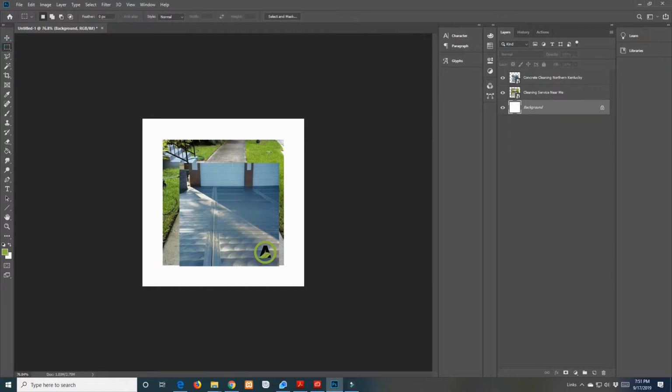Your shape tool. So I'm not going to really go into the shape tool right now. You can just draw shapes. So we're on square, so it's drawing a square. If I do, you can do a circle. If you just left click and drag out, it's going to get all distorted. Control Z it. If I hold Shift, we are staying in proportion again. So Shift and Alt are basically your two keys that are going to help you keep everything in proportion. So if I hold Alt and do it, nothing. So Control Z.